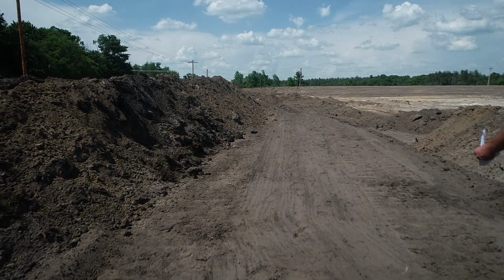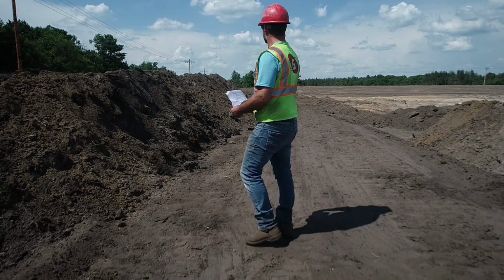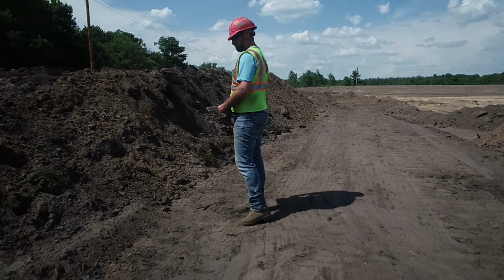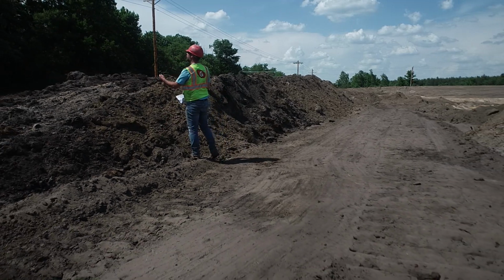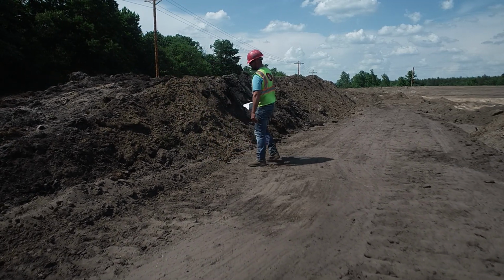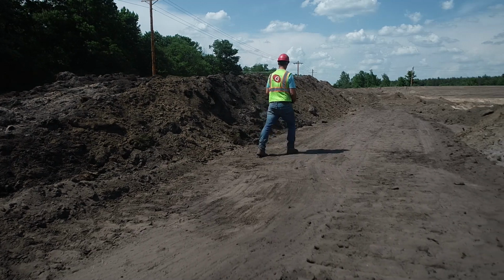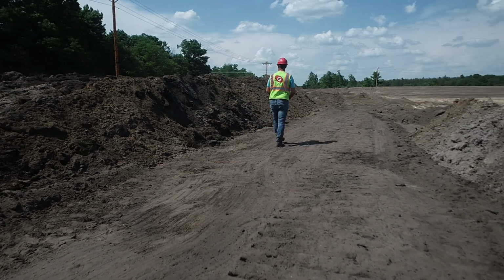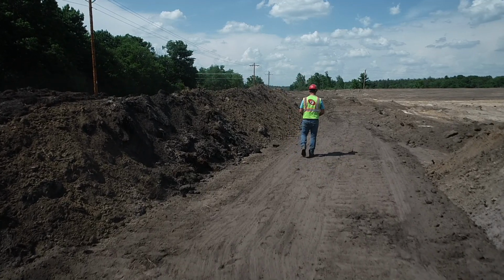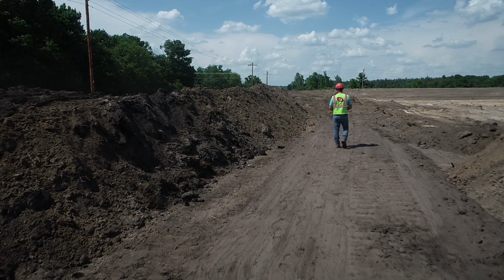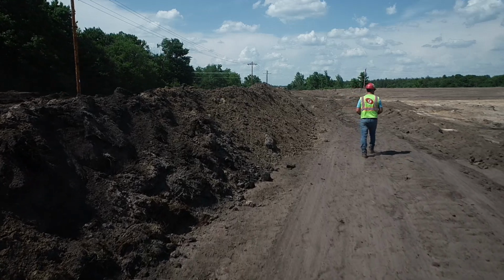Dozing procedures and precautions. Workplace exams. A competent person should look closely at any work area around a drop-off for signs of instability, including cracks, sloughs, or changes in seepage or adjacent water levels when conducting an inspection. The grade of the slope that is safe to work on is determined by such factors as condition of the ground, load being handled, and the type of dozer.